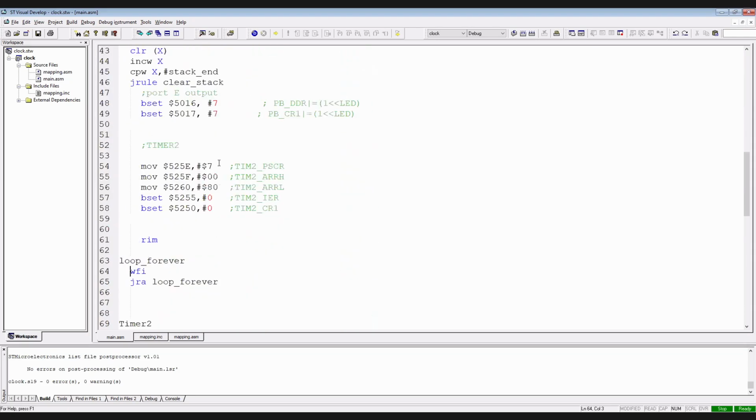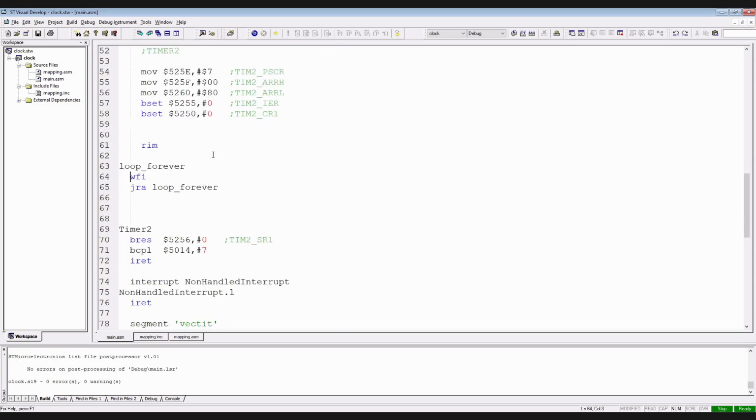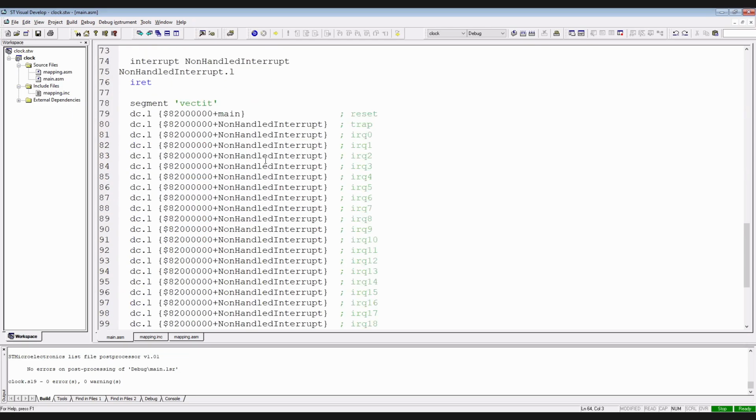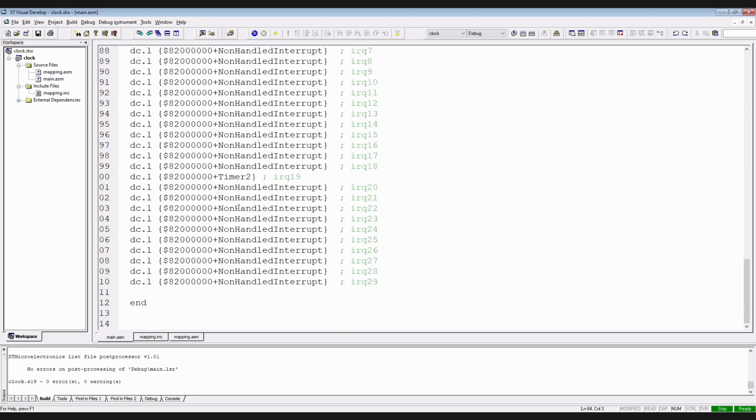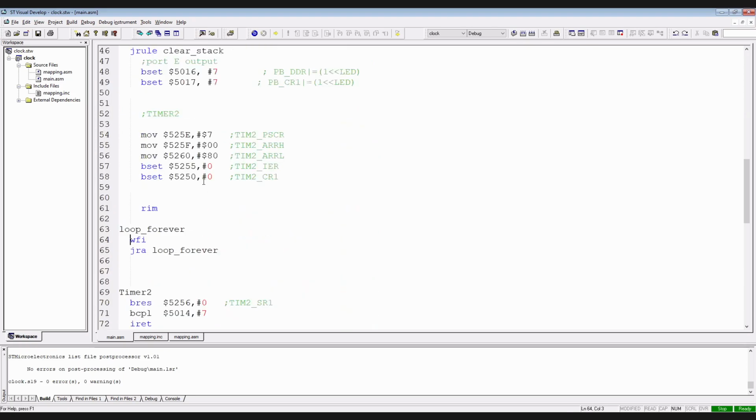Please try to create a new project and exchange the default generated code by pasting only this part, without changing the mapping ASM and any other files. It should be able to compile and build, and then you can debug.